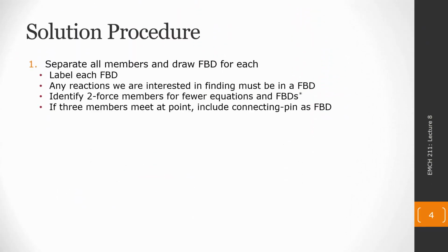Well, since most of the time we're going to have these statically indeterminate systems, I'm going to recommend always skipping the external free body diagram and jumping right to separating all the members of your frames and machines into their individual parts, and then individually draw each of their free body diagrams. We want to give each free body diagram a label of some sort so that when we go to write our equilibrium equations, we know which sum of forces it's coming from, which sum of moments it's coming from, which diagram do they pertain to.